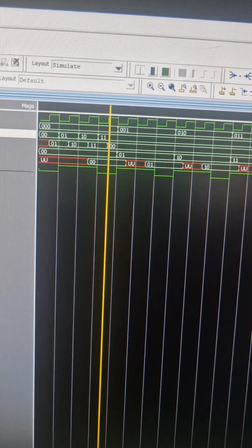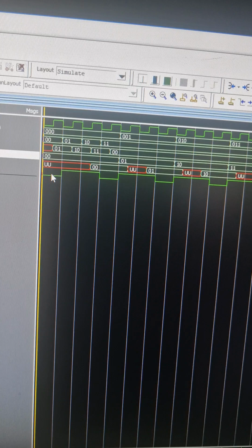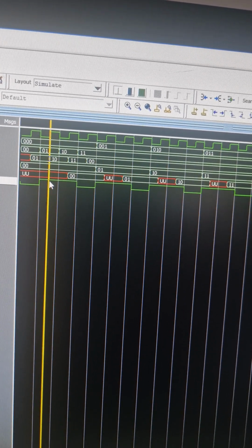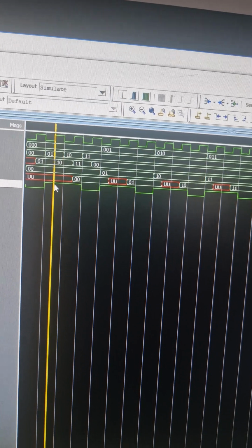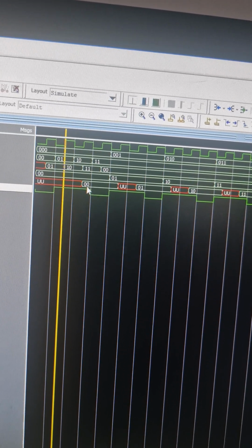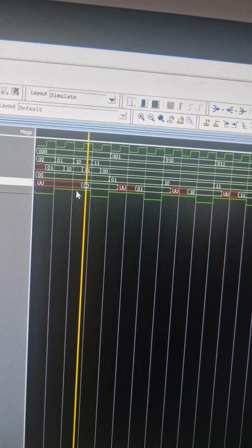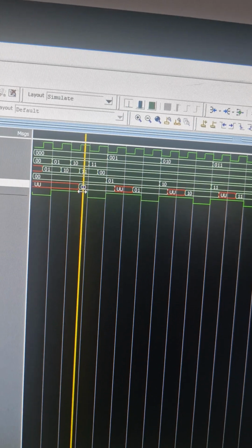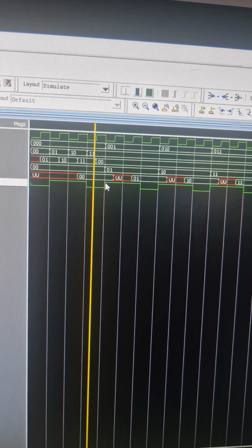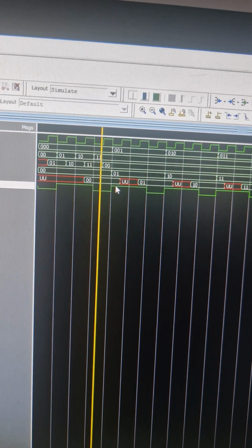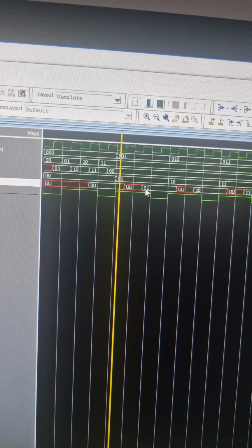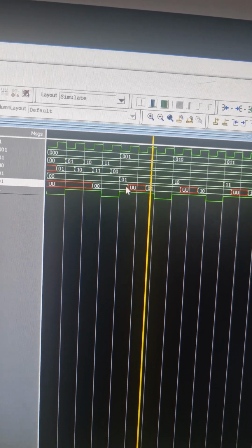But for the RAM operation, as you see here, we have zeros in VRAM, so we cannot write anything. Then once we have 1 here, we can say that our address RAM, our data RAM and the QRAM starting from here, data RAM and QRAM are the same. It takes a little bit of time at the beginning, and then we set the VRAM again to 0. Then again, after only 1 clock cycle, we set it to 1. Once we set it to 1, you see that QRAM and data RAM take a little bit of time in here. Then they are both the same, because we wait